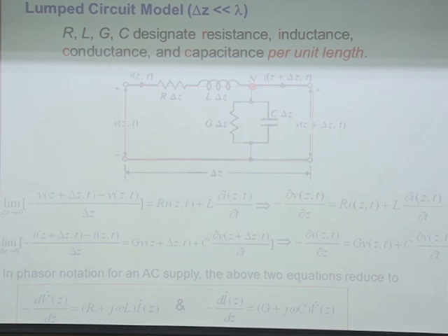Okay, so for example, this equation, well, this is a spatial derivative, so just keep it there, but convert this into the Phasor. On the right-hand side, you have differentiation of the current with respect to time. So drop J omega right here, and then convert this current into the Phasor notation. That's it. Very simple operation.